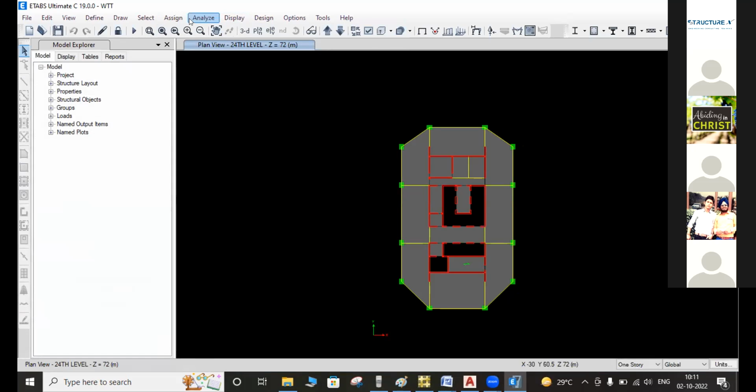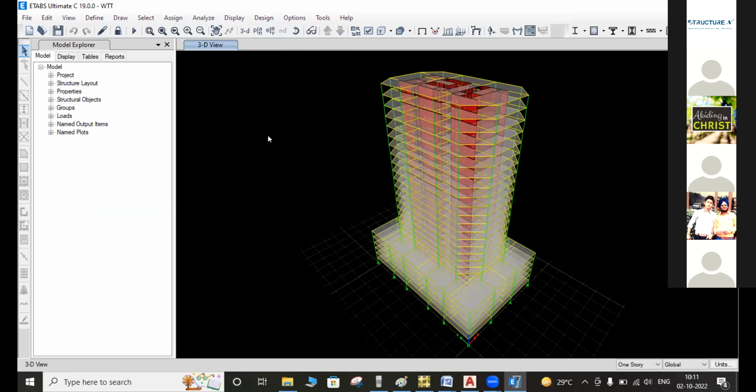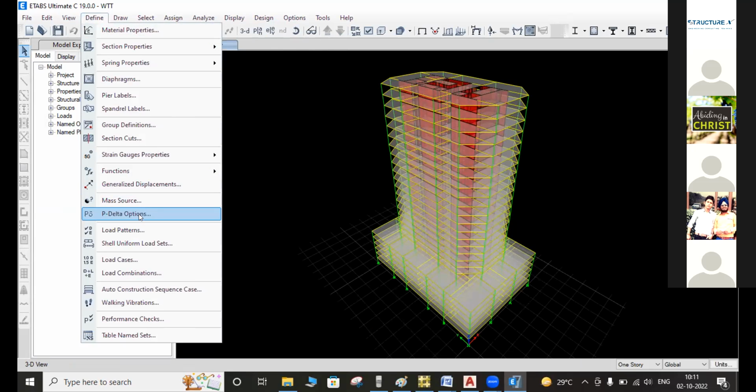So, performing the dynamic analysis, we identify the lateral displacement, story stiffness, and story drift. These types of checks have to be considered, but we are moving once again to our dynamic behavior. If we have geometrical irregularities or nonlinearity like P-delta, how can we handle all these after this? These are the linear dynamic analyses we considered. The other part is the geometrical nonlinear analysis, just the P-delta. So just wait 1 minute. Here we have the list of... kindly stop sharing screen, Karim.